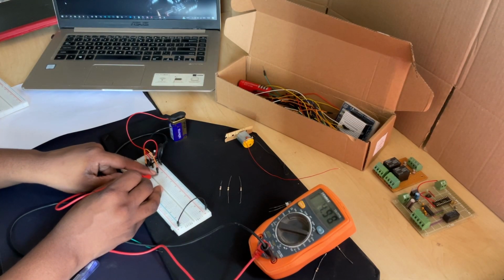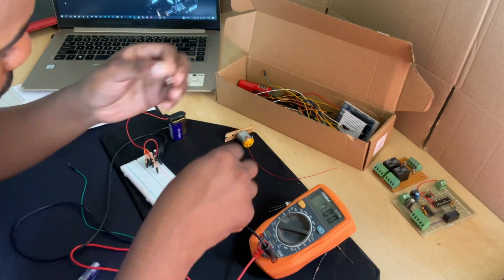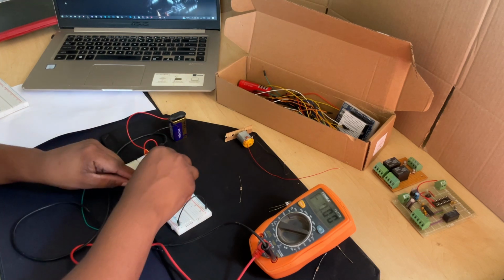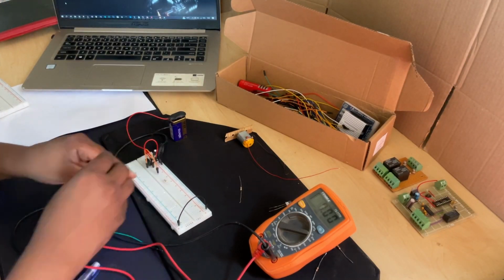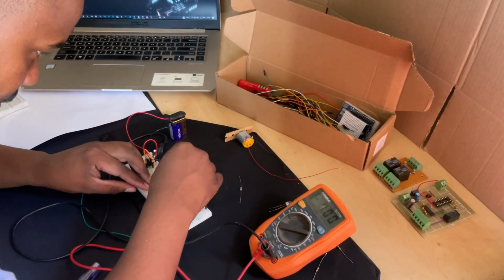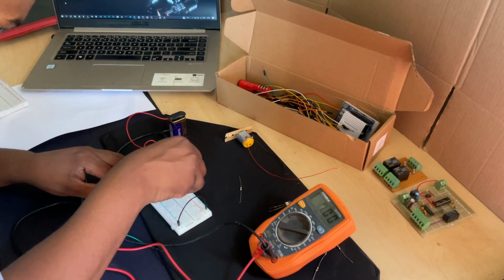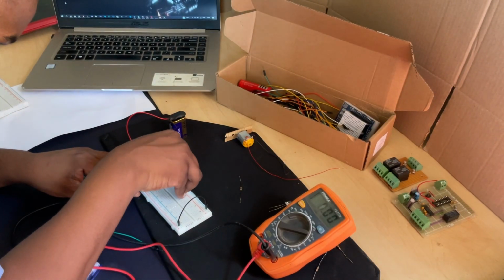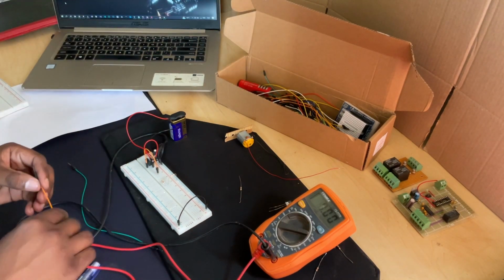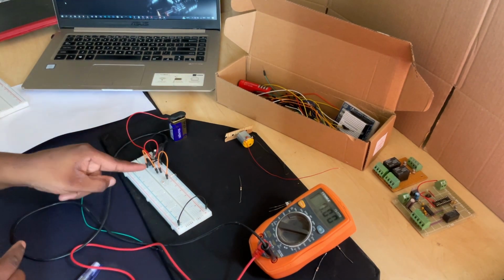The first circuit we're going to build is as shown. We're going to put two resistors of 1 kilo ohm resistance in series, and we want to measure the current and the voltage. And there we have placed our resistors in series. Right, so now we can take some measurements.